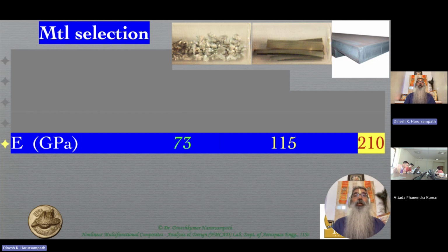But nonetheless, the elongation at that level, for most metals and metallic alloys, is of the order of a few percent. It could be of the order of 1%, 2%, 4%, 5%, and so on. So in terms of orders of magnitude, the non-dimensional value is 10 to the power minus 2.